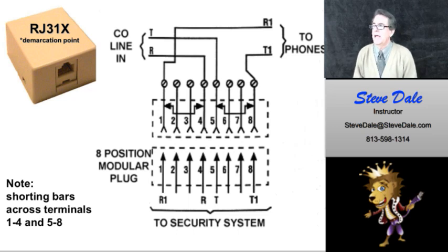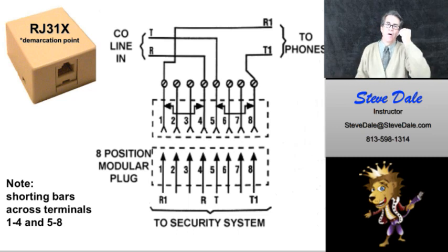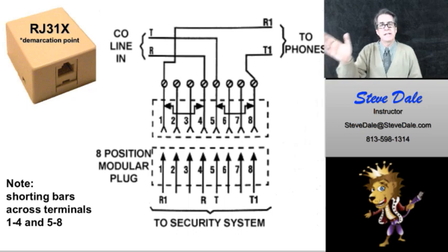And that's a problem, because if Granny is on the phone and the house catches on fire and she drops the phone and it's off the hook, if that panel can't disconnect that phone, that means it's not going to get dial tone.